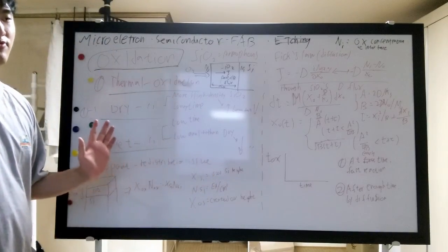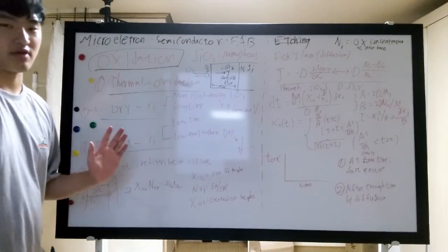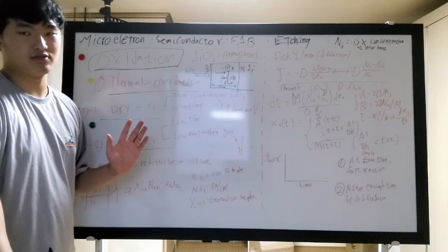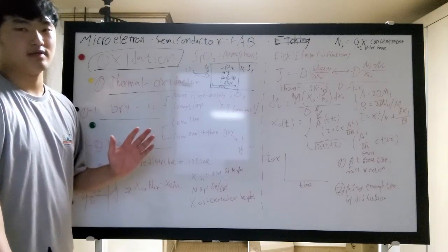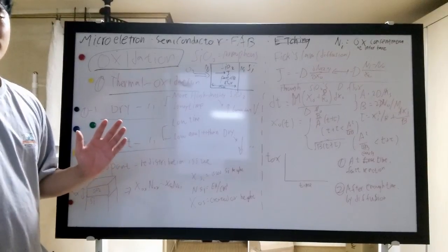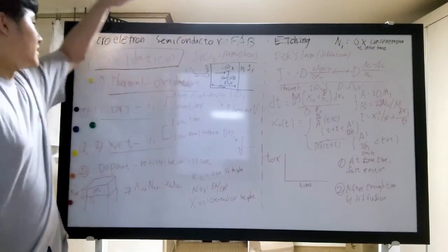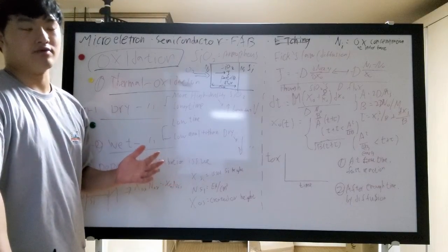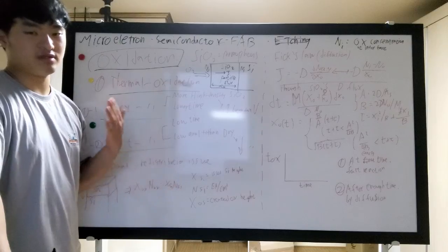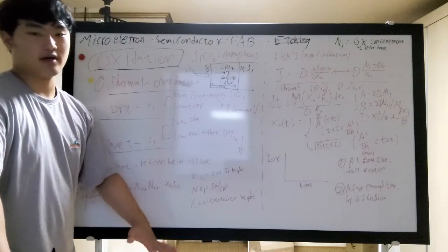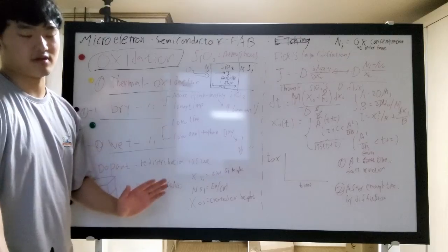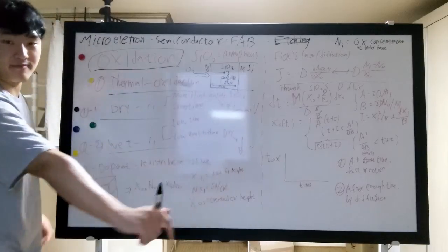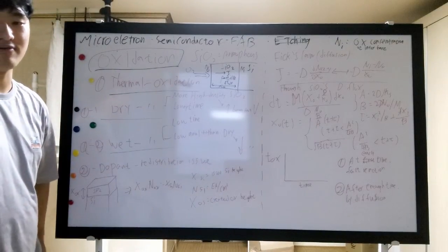Taking the example of the MOSFET or the MOSCAP, the silicon dioxide will block the channel's injection to the gate, and it will finally make the channel. And for lithography, the silicon dioxide will block the light from being injected to the silicon wafer underneath, and finally it will work as a mask. So SiO2 is commonly a type of amorphous.